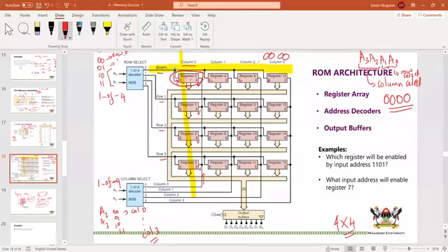Now, I'm reading, obviously. Let me remove that one. Okay, so we can see that because I activated row 0, it is high, and column 0 is also high. We can see that this high comes here, and for column 0, that high also comes here. Although, of course, the high also comes here and there, but on this side there are zeros, so those registers are not enabled. Now, we see that if we are reading, the information comes to that bus.